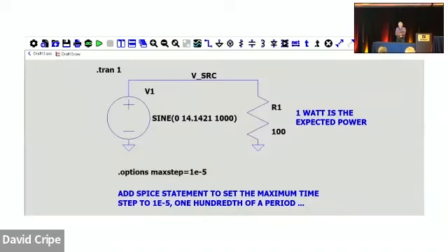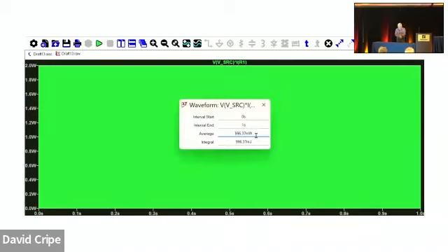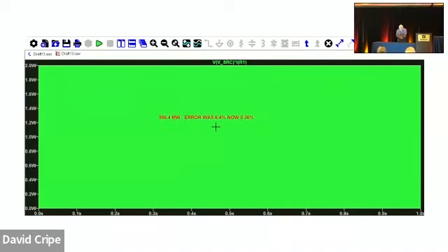And recall the power measurement before. We're going to do that one again, having run the analysis at that time step. And now, when I right-click on that instantaneous power waveform and read it, it's 996 something. So what I've calculated out, it's going to pop up there in red. You can see it. Well, I think it went from 6.4% error to 0.36% error. So that's just another tool to keep in your hip pocket. If things aren't looking right, you can consider changing the maximum time step.